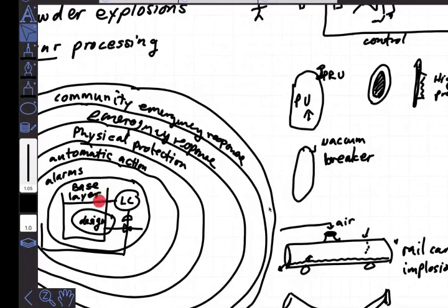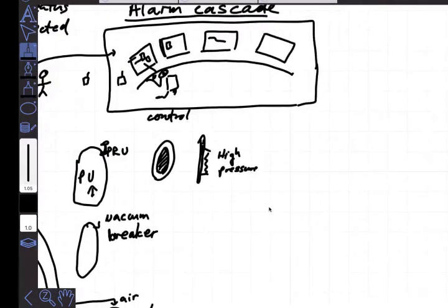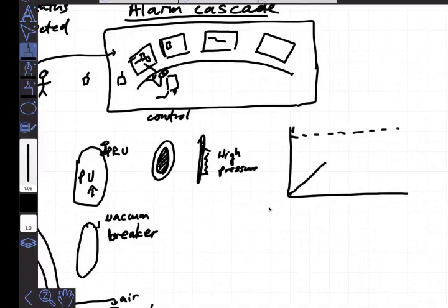The novice version of that alarm has the alarm right at the lip, at the top here, saying, hey, it's super high, the level is too high. The problem is that if it's right at the lip, by the time the operator can take action, close a valve or open a valve or stop a pump or whatever, the tank has already overflown. So an intelligent alarm happens well before the limit. If we were drawing the level creeping up, let's say this is overflow.